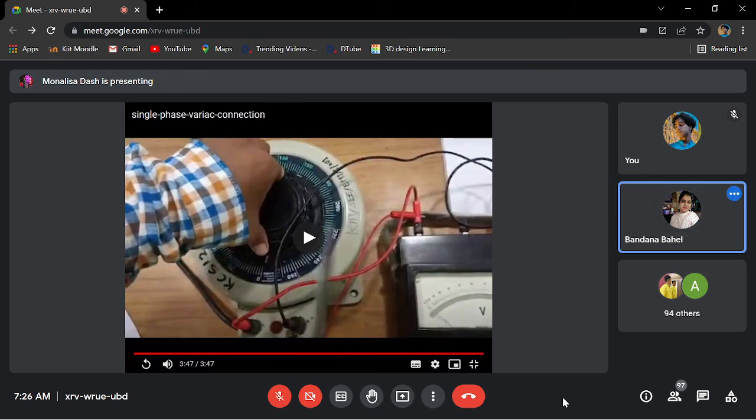Okay. So the specific thing is that it has one winding and it is also known as single phase auto transformer. Is it clear? Yes. Okay. So you can't really say step up, step down function. Obviously, if you consider it from 0 and it is taken to 230, then it is stepping up, but it will only do as much as the supply voltage given to it, max to max. It will not go beyond the input supply voltage, okay? So okay, the variac is clear.